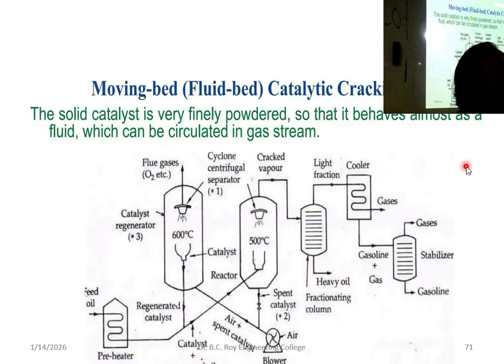That heat and pressure, compression means pressure also, can convert some of the molecules into small fragments, and that gives radicals: methyl radical, ethyl radical, propyl radical. These radicals can give a chain reaction, and as a result more heat is generated and combustion starts. Once combustion has started, it happens by itself without any spark plug.